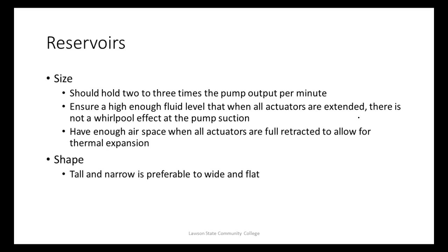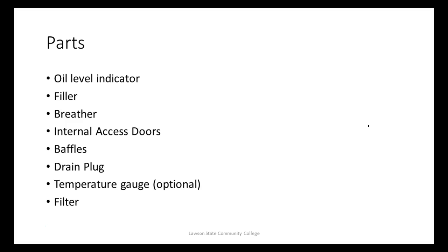Ensure a high enough fluid level that when all actuators are extended, there's not a whirlpool effect at the pump suction. Have enough airspace when all actuators are fully retracted for thermal expansion. Shape tall and narrow is preferable to wide and flat. We okay?